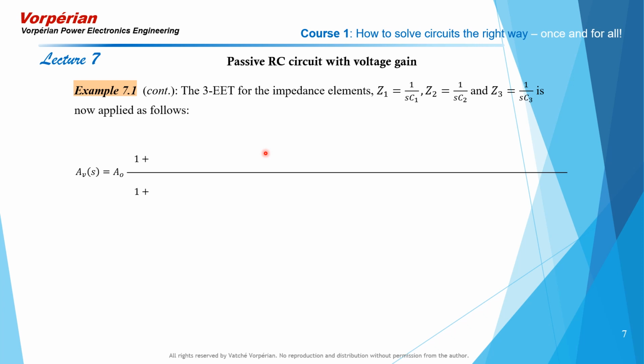All the calculations in the numerator are performed with the response of the transfer function nulled, and all the calculations in the denominator are performed with the excitation set equal to 0.